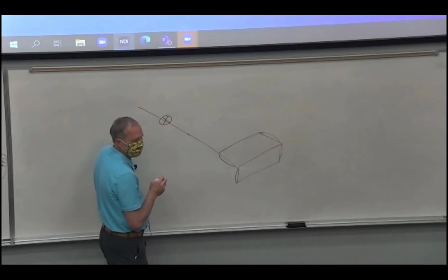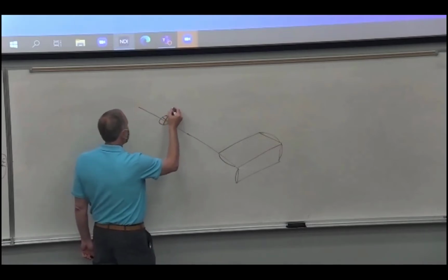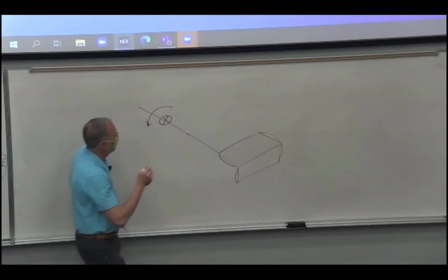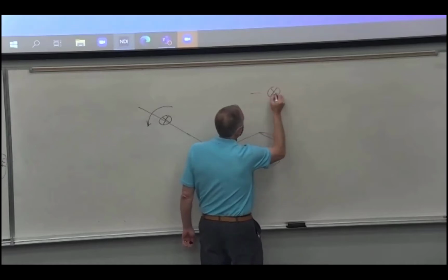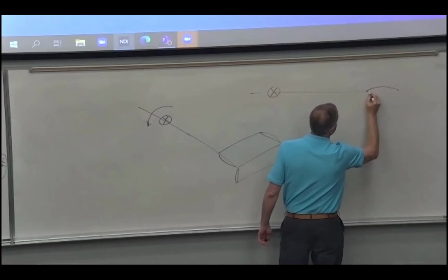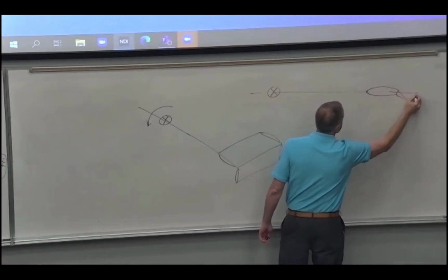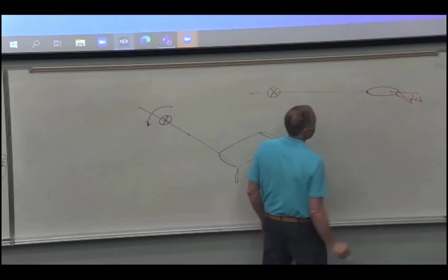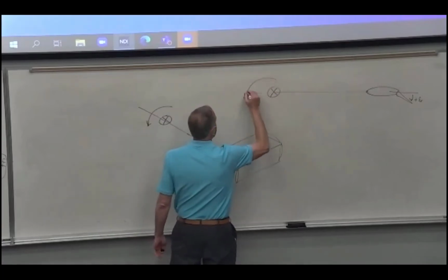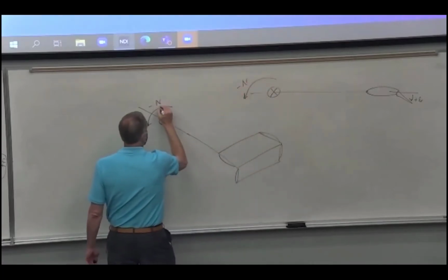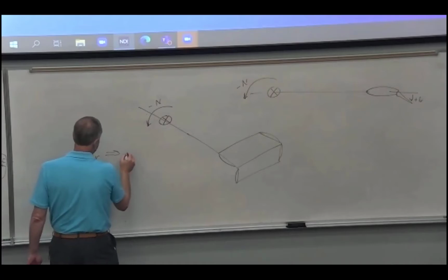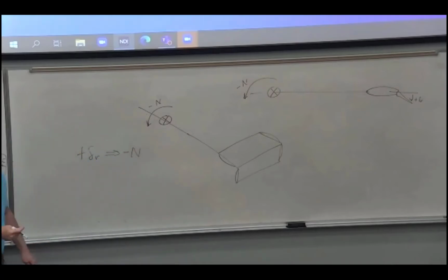So with the rudder deflected like that, positive rudder, which way does it produce as far as yaw? Let me draw a top view. Right, that's what this is by definition, positive rudder, right? So which way does it yaw the airplane? Give me negative. So positive rudder produces negative yaw. And that's just how it's connected up.